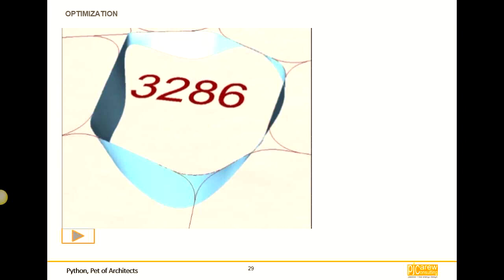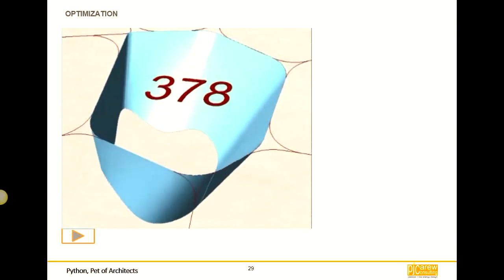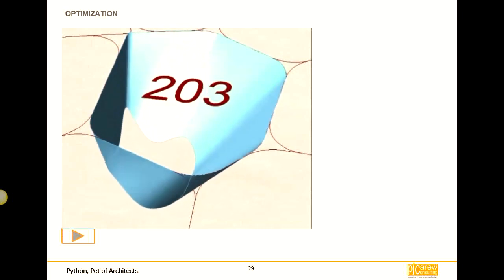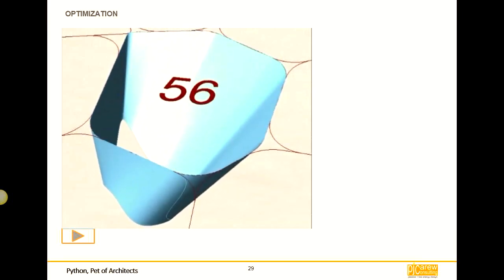For example, in this case, this is just one cell from the skylight, which had almost 3,300 hours of glare problem. By optimizing the geometry, we get less problem, and the program optimizes the glare issue with the minimum fabric usage. So we had different criteria for this optimization.